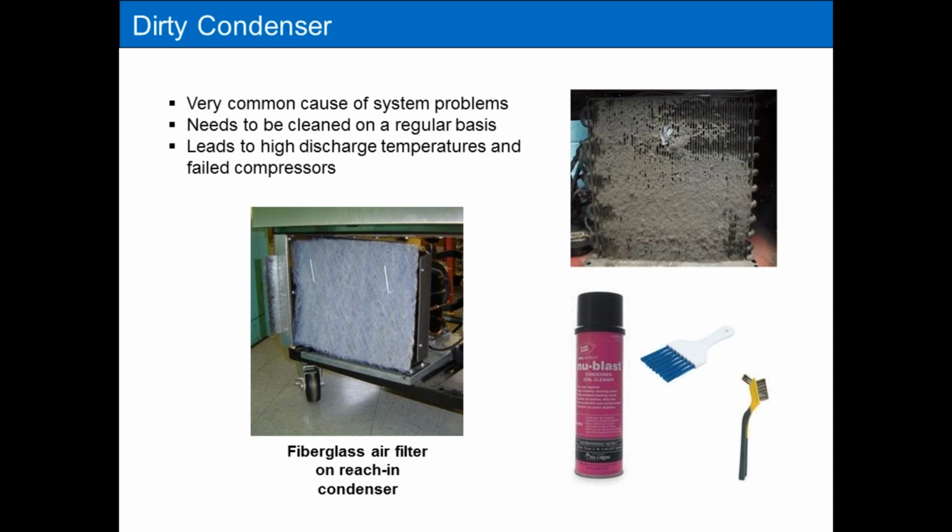There's two scenarios you're going to run across when you're looking at these condensers. One is going to be dirt, like I'm showing you on the screen here. That's going to be pretty simple for you to clean. But sometimes in a really greasy environment, if it's in a food lineup next to a fryer, these things can get impacted with grease, and that's pretty problematic and pretty difficult to clean. Sometimes you're not going to be able to do a good job cleaning them because the grease is rock hard. And there have been some occasions where it might be best practice to just change out the whole condenser or condensing unit if the compressor failed, because you just can't clean the coil.